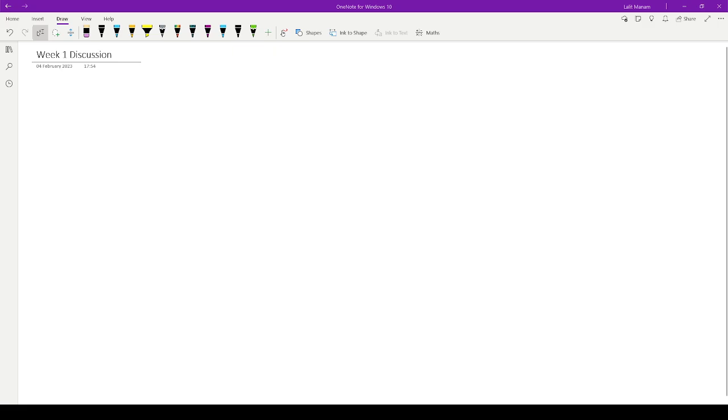So quantization is done over the signal value and sampling is done over the space. I hope this part is very clear. When sampling of space is done and then quantization of the signal is done, we get a digital signal. It has nothing specific to do with space. It can also be done across time. If someone among you has done digital signal processing, you generally see data which varies with time. There you sample across time, and then the amplitude values are quantized to get a digital signal.